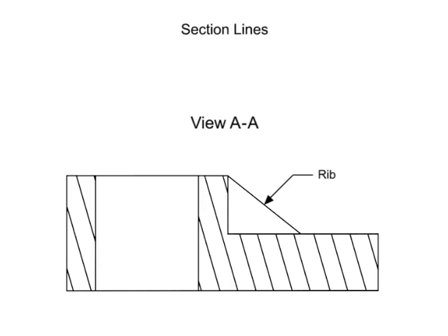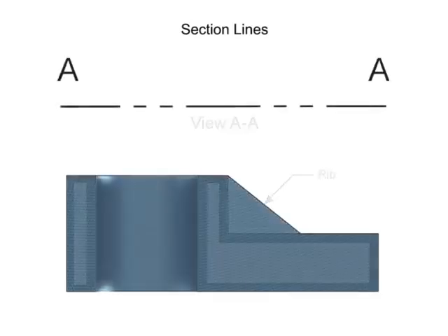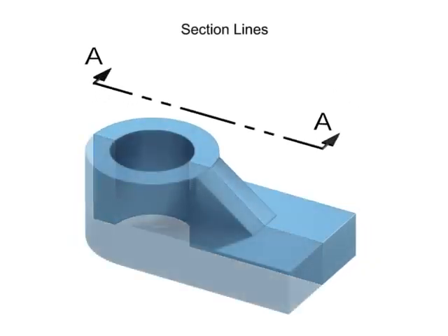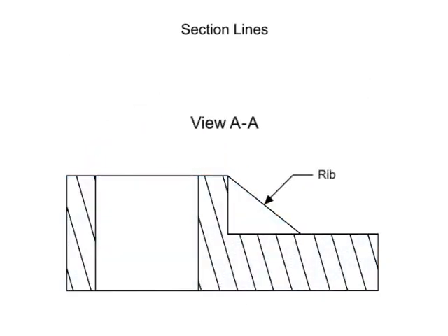Additionally, if a drawing is clearly illustrated, section lines are sometimes only drawn along the visible lines along the exterior of the sections. Large parts are often drawn with outline sections. There are a number of different types of sectional views that can be drawn. This is a full section view, generated when the cutting plane passes through the entire part.